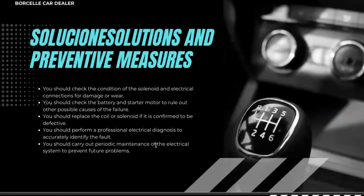Solution and preventive measures. You should check the condition of the solenoid and electrical connections for damage or wear. You should check the battery and starter motor to rule out other possible causes of the failure. You should replace the coil or solenoid if it is confirmed to be defective.